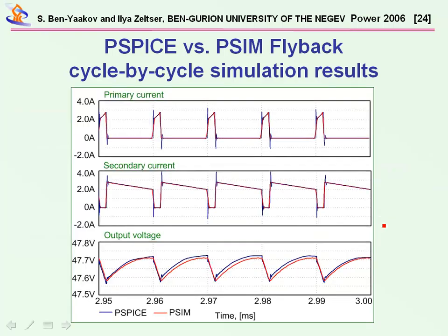If we put one result on top of the other, on the average, of course, it's very good, but lacking in the PSIM will be all these transitions that, for checking the performance of the circuit and in understanding how it works, are really not important. Not only that, it's good that you don't have to handle these spikes.